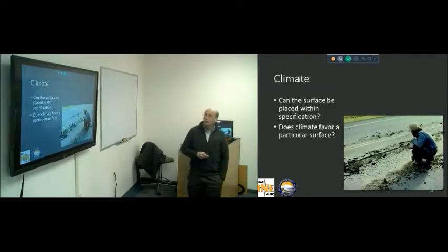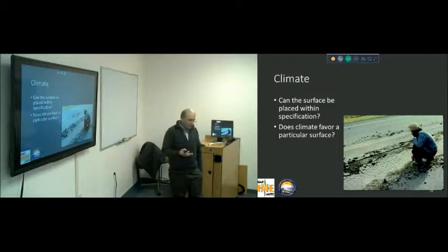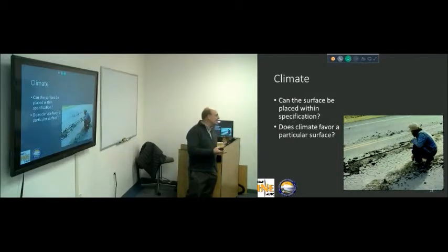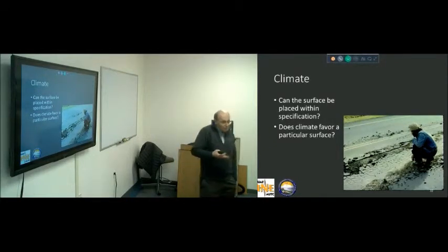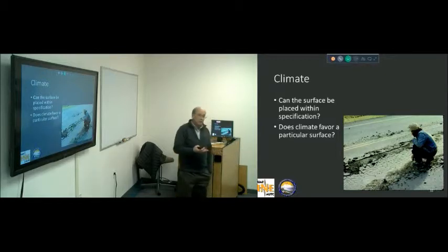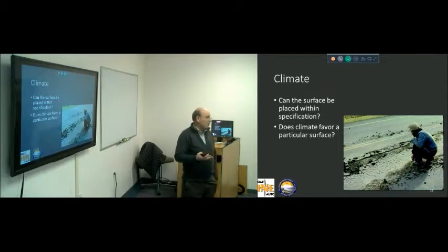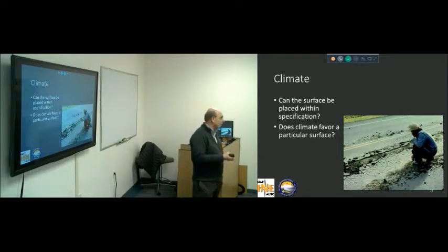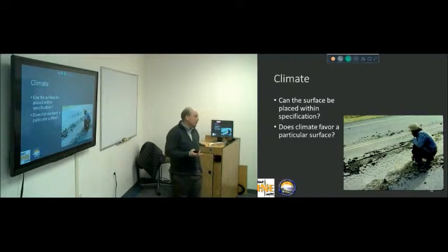Climate: within the climate that you've got, can it be put in within the specification? If you're anticipating it being put in late in the year, you can run into problems if you don't have the right material, or maybe you shouldn't do it at all. Sometimes you're forced into it. I've been forced into it because the director says that will not sit as gravel over the winter. So do I put temporary pavement in, or do I put in something that hopefully will work? Stabilized base, oddly enough, works really well in that situation. It gives you something down that you don't have to take up. I've done it at zero, and it's still there. It doesn't mean you can't do it. It's just you've got to put in a lot of effort.